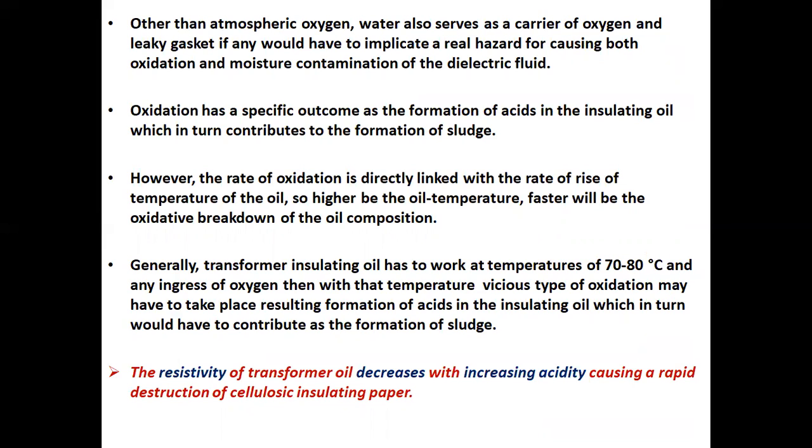Oxidation has a specific outcome as the formation of acids in the insulating oil, which in turn contributes to the formation of sludge. However, the rate of oxidation is directly linked with the rate of rise of temperature of the oil. So, the higher the oil temperature, the faster will be the oxidative breakdown of the oil composition.